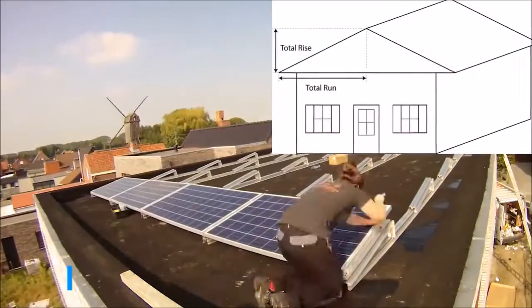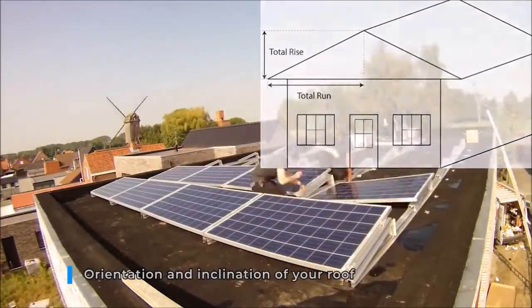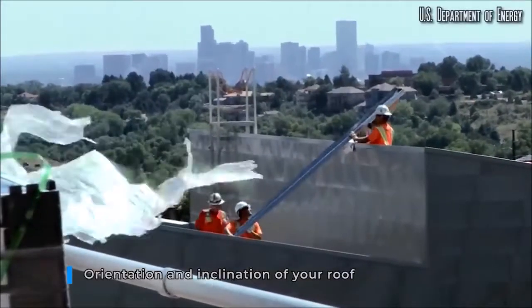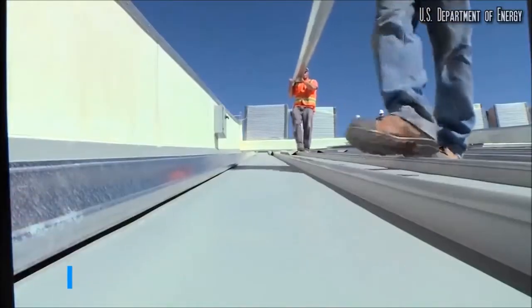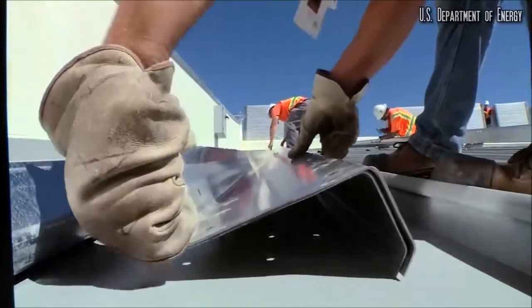The orientation and the inclination of your roof are also important. To produce maximum electricity, solar panels should face south and your roof should have an inclination in which the sunlight hits vertically on average during the whole year. The more you go up north, the steeper the inclination of your roof should ideally be.